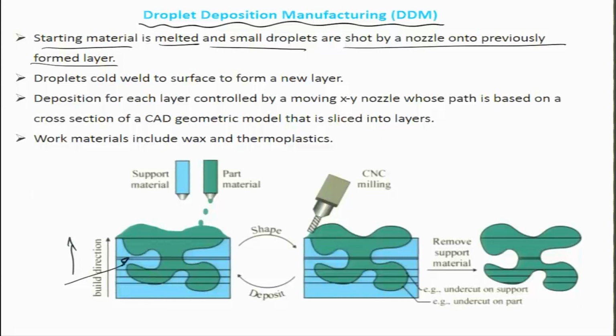So what you are essentially doing is you are having the nozzles typically loaded with two different materials which are molten. One is the material which would formulate the part, the other is the support material which would come off. Support material could typically be a wax layer again, which could be melted away, and so the part can get out. The wax is just a sort of housing for the part,